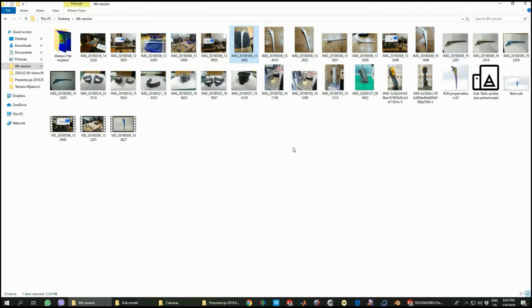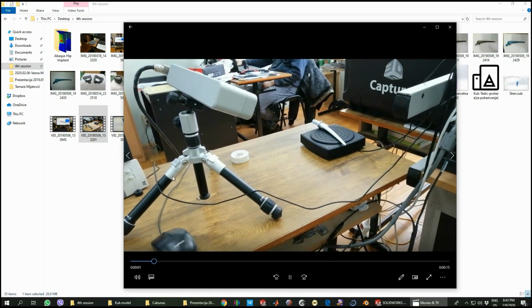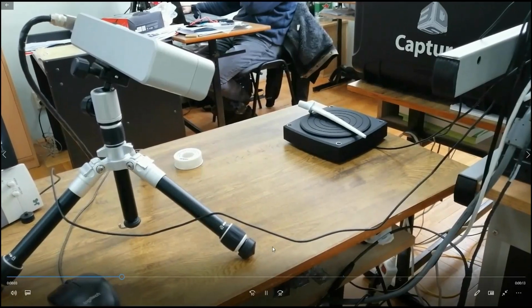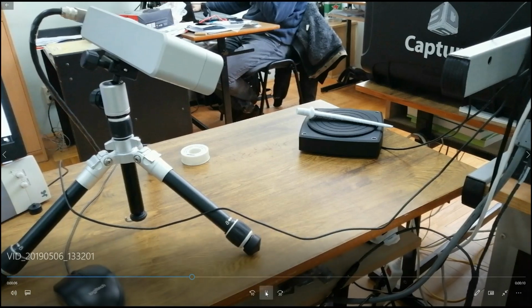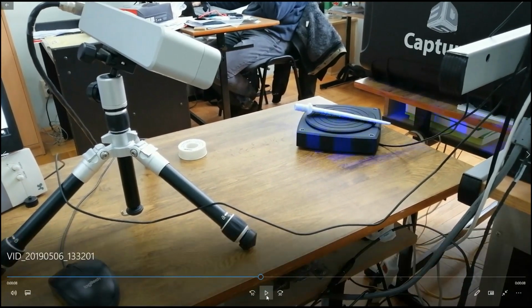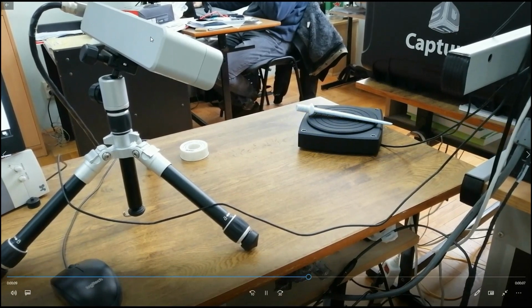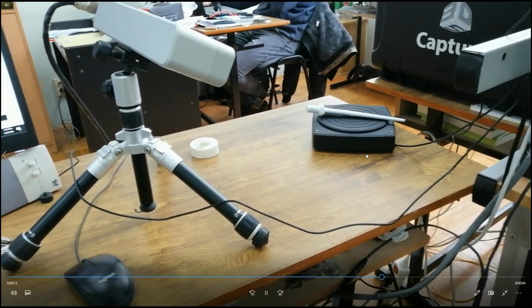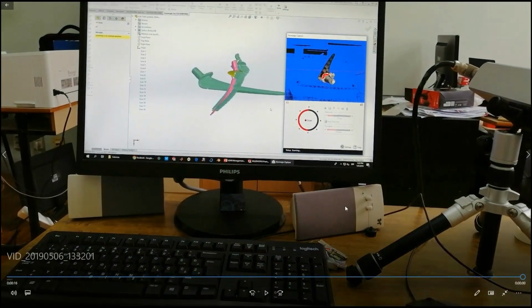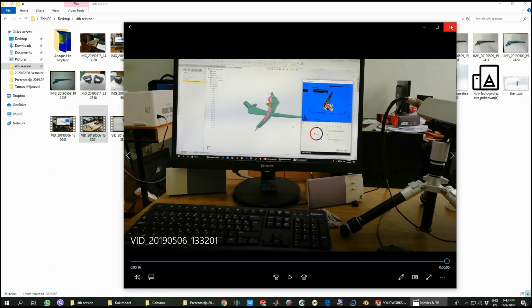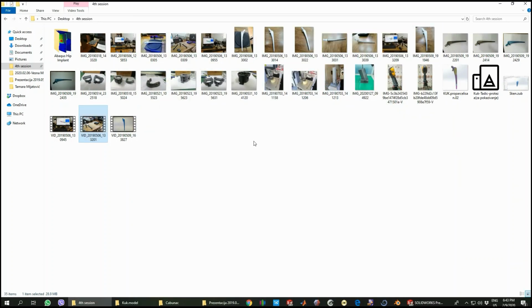So, what does a 3D scan look like? Here you see the turntable turns and stops. The scanning head illuminates a blue light, and during that time two cameras record a section. Then it will continue doing the same thing in the next section. Let's look at the longer video.